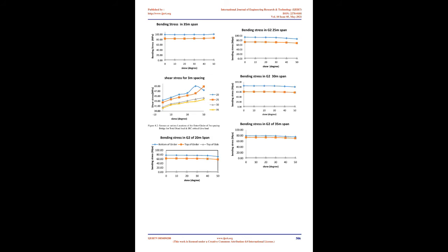The basic cross-sectional dimensions of all bridges considered in this study are shown in the table. The symbols used in the first column of the table represent designations of the bridge types considered. DEG stands for skew angle, G stands for number of main girders, and the number in the middle of the designation represents the span length in meters. For example, 5G2530DEG denotes a simply supported bridge of 2-lane, 5 girders with 30 degrees skew angle and 25 m span. The cross-sectional symbols used in the table are shown in Fig.